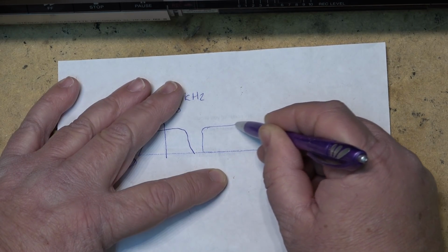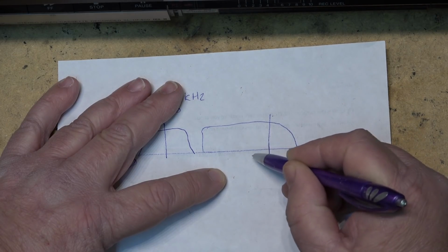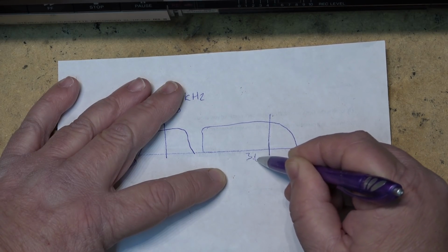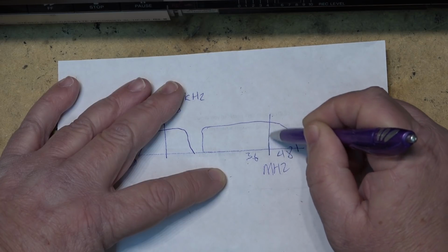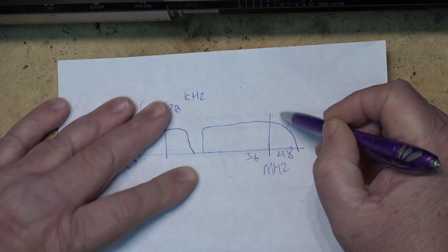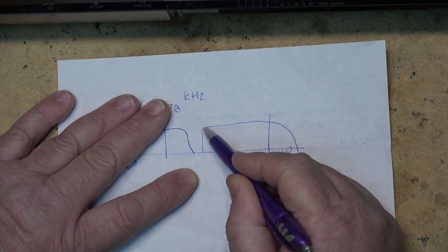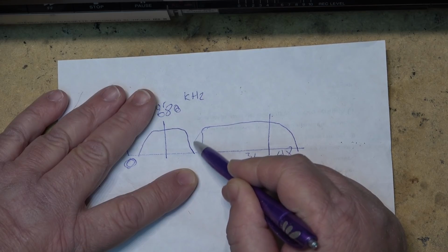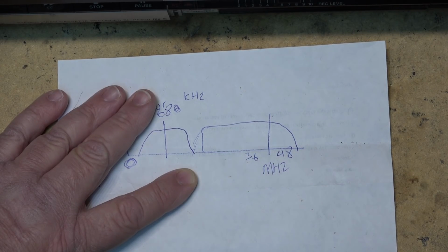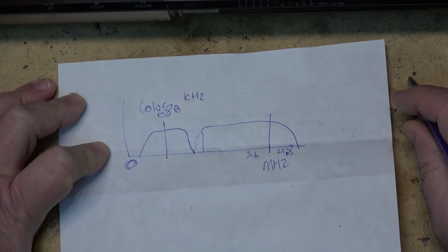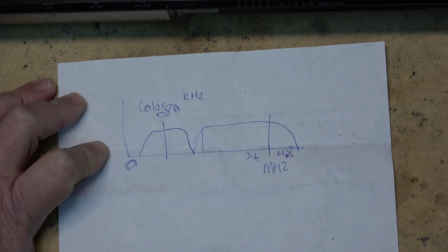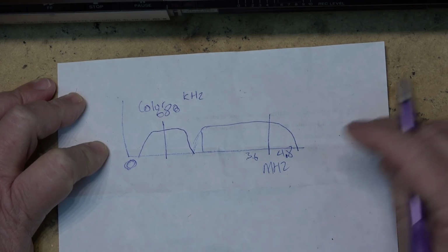This is for the luminance, and it rolled off like that, and it was basically 3.6 to 4.8 megahertz. This was your carrier centered, and your lower sideband extended down to pretty much where the color cut off, like down like this. This was the standard mono Beta. VHS was 3.4 to 4.4 megahertz. I forget. I think it was 3.6 to 4.8, because this was standard Beta.